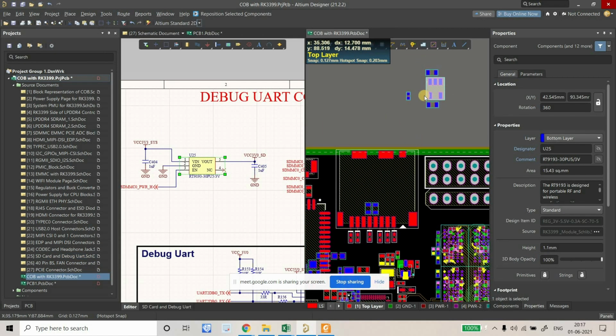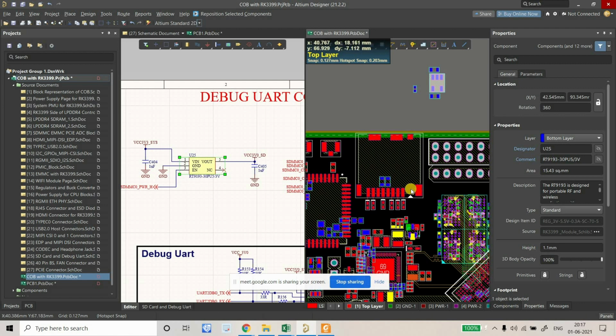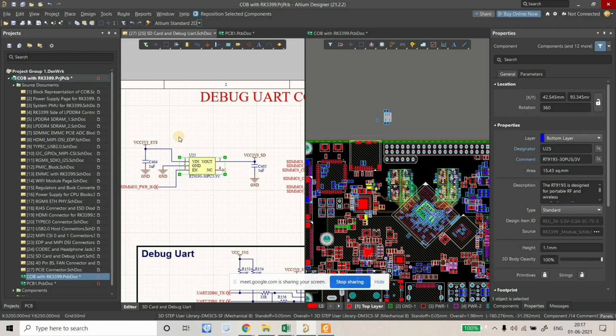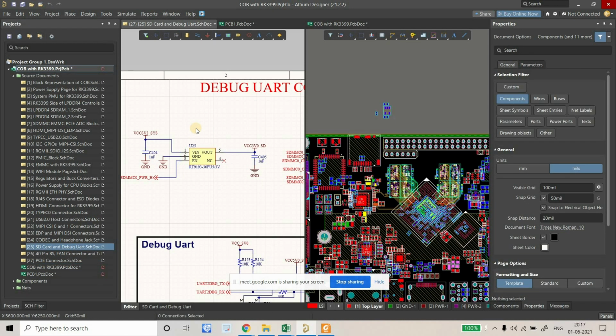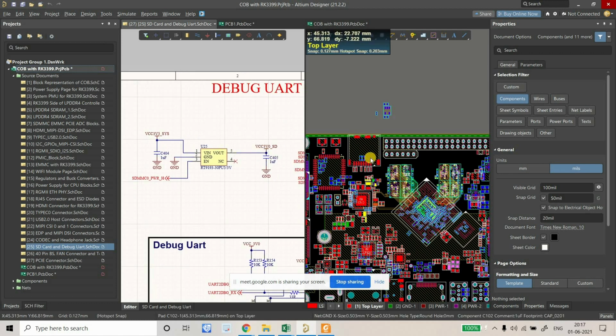At the time of first placement, I planned where I have to place this component. We don't have so much free area in this section. And if you remember the block diagram that we did in the earlier session, all the regulators and the PMIC will be powered through the 3v3 system, and that 3v3 system is coming from a buck converter, and that input is, I guess, 5 volt. So you can see everything is coming from 3v3.